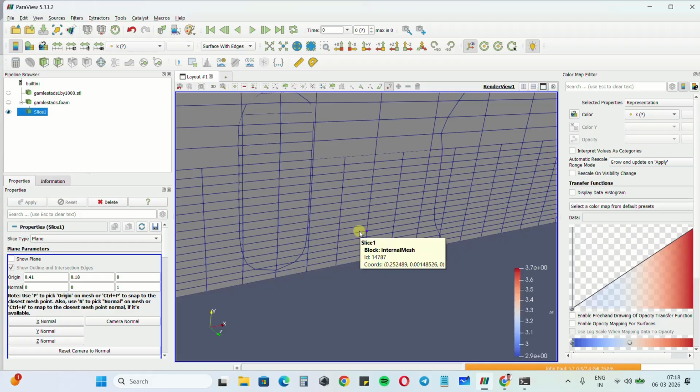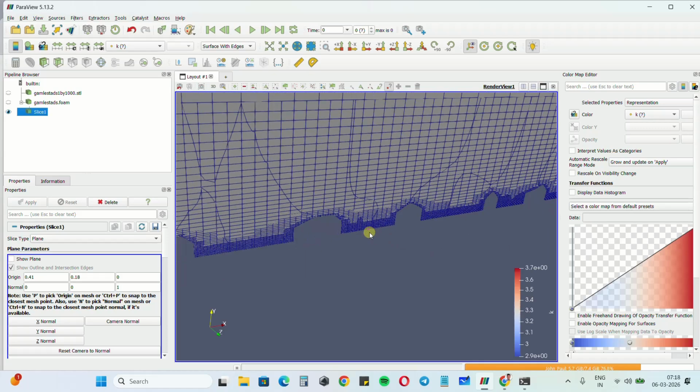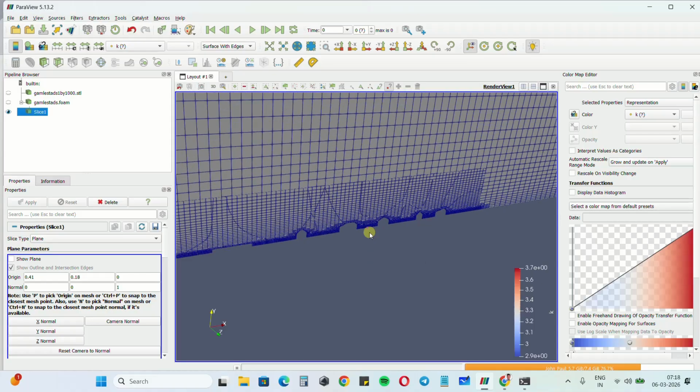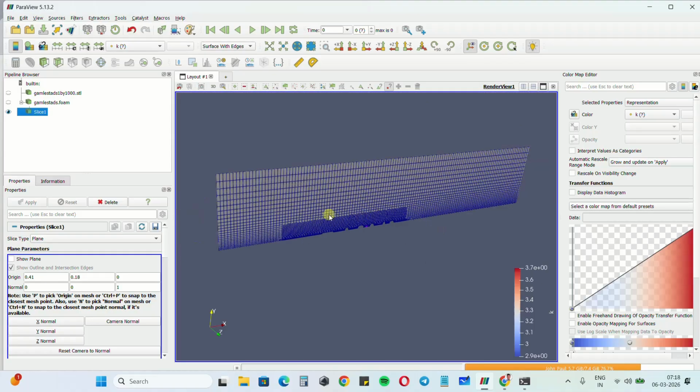I think this is fine. Maybe you can have a bit more refinement so that it satisfies perfectly, but having a small jump in refinement at this stage will explode the number of cells, and it's already 3 million, so I think it's okay for the time being. So this is our final mesh, and now we can set some post-processing functions and then rerun the simulation.